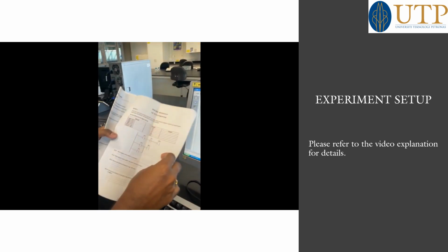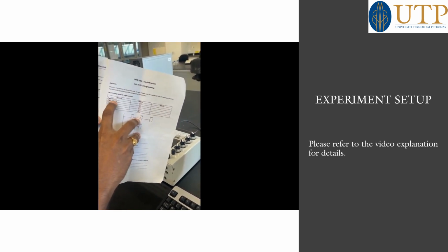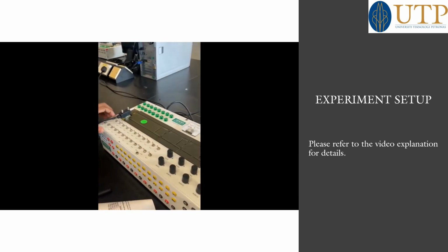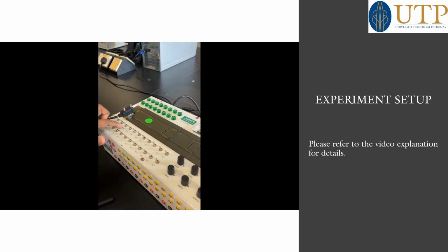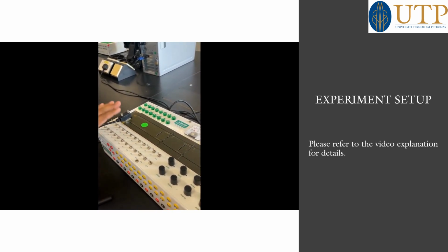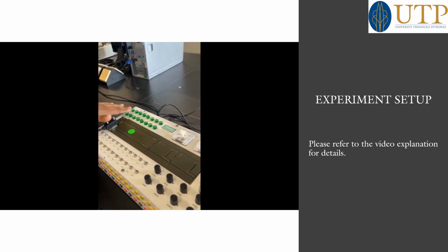In the symbol table you need to give symbols. It is just for representation like this. So for inputs I0.0 we'll give toggle switch S1, toggle switch S2, like that. Okay, so the inputs are given here. All the inputs are noted with I0.0, 0.1, 0.2, and the outputs are given with Q0.0, Q0.1, Q0.2, like that.